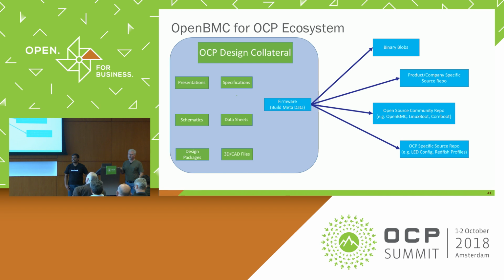Good question. So I think I should give a history for this. The whole OpenBMC started with Wedge. Back in like 2015, all the BMCs were meant for server management. Storage systems used enclosure management, either a SAS expander, SAS controllers, or PCI controller vendors. They used to provide this enclosure management functionality. And switches never have the BMCs at all. They have this control plane and data plane. In the control plane, the x86, there is a small processor that manages the fans and other stuff.